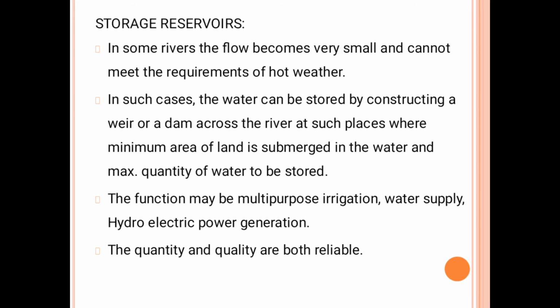Then storage reservoir. In some rivers the flow becomes very small and cannot meet the requirement of hot weather seasons. In such cases the water can be stored by constructing a weir or a dam across the river at such places where minimum area of land is submerged in the water and maximum quantity of water can be stored. The quantity and quality are both reliable for storage reservoirs. The functions of a storage reservoir are normally irrigation, water supply, and hydroelectric power generation.